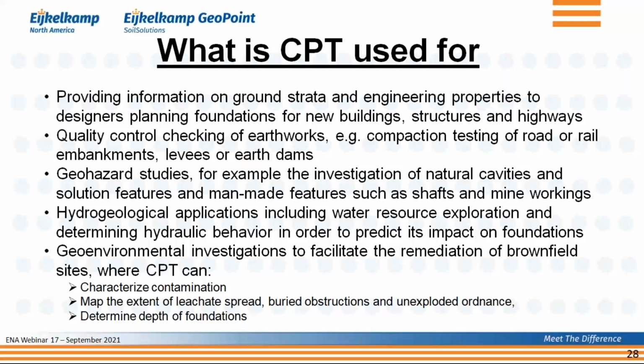Because as you're pushing the cone into the ground, you can put all kinds of other instruments into the ground that, because with the cone you can go much deeper, may be very informative on what you have in the soil. A good example of that was the magnetometer that we talked about earlier. Normally it has a range of about 7 feet, about 2 meters, but by pushing it into the ground, you can get information from much greater depth.